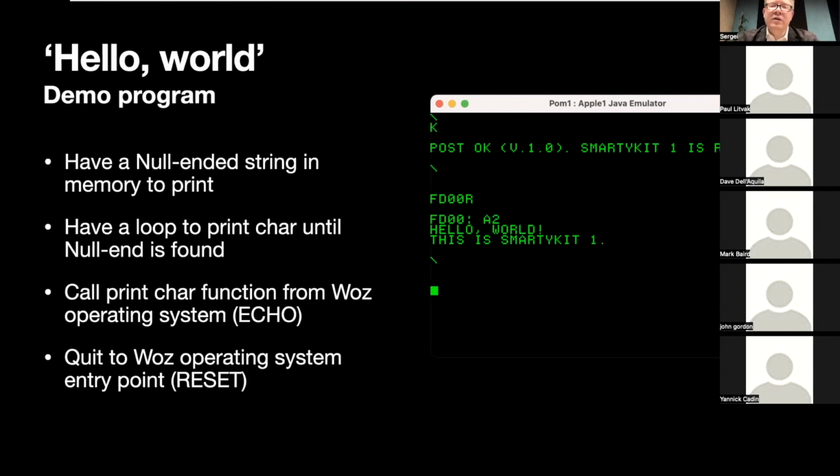And so you can download this makefile and all this ROM development folder from this link I've shared with you, and you can modify this assembler code to add different sorts of strings, modifying this hello world example. Then you can build it and load it to this ROM, and you can run it even in the emulator and check how the 6502 really works.